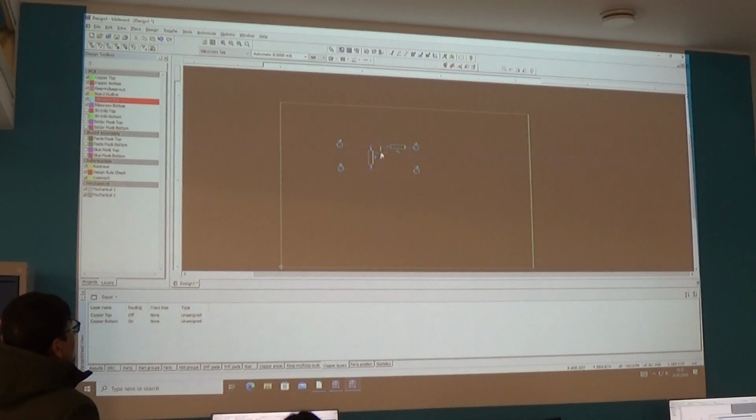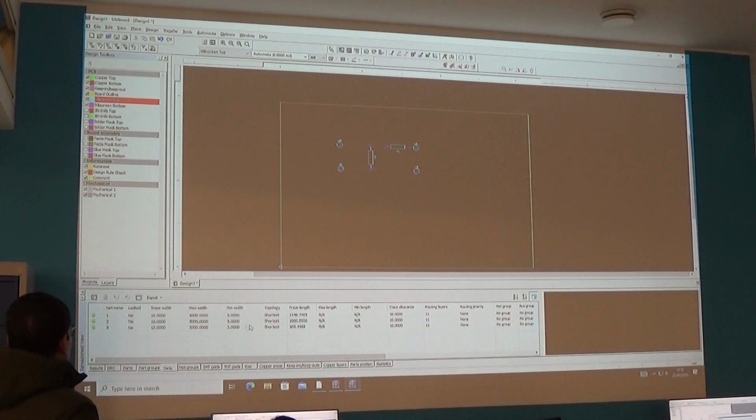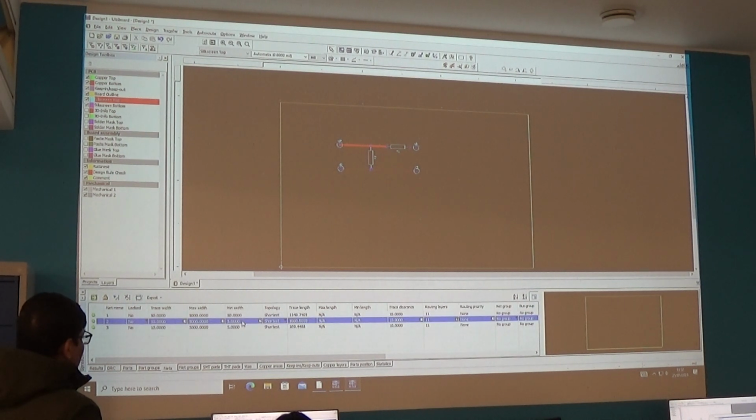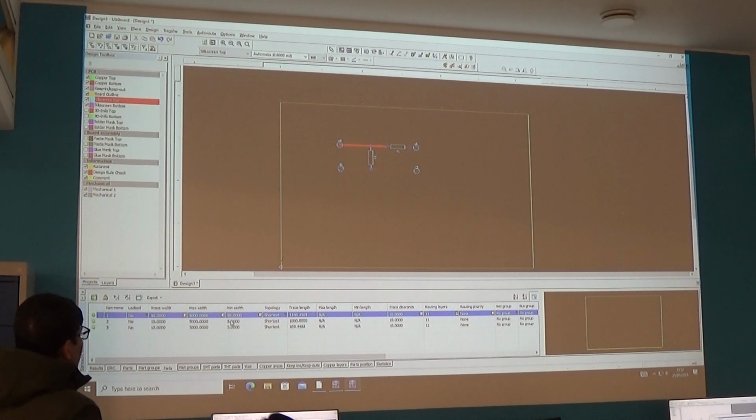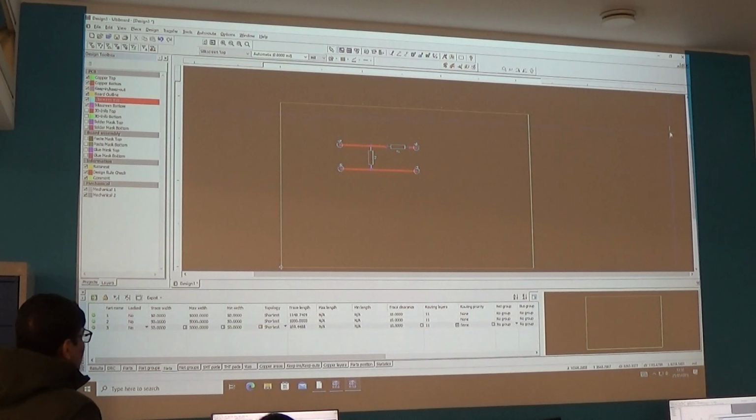But the copper pads are so thin, they're thinner than a hair, actually, what you see there. So I need to go a lot thicker than that, so I'm going to go to nets, and I'm going to set the minimum width to something that's a bit more sensible. And I reckon 50 is about it, that's what I'm going to opt for. And you can see that my track up above has now gone a lot fatter than it was. There's the 50 in there, and there's the 50 in there. So that looks a lot more like a sensible printed circuit board now, doesn't it?